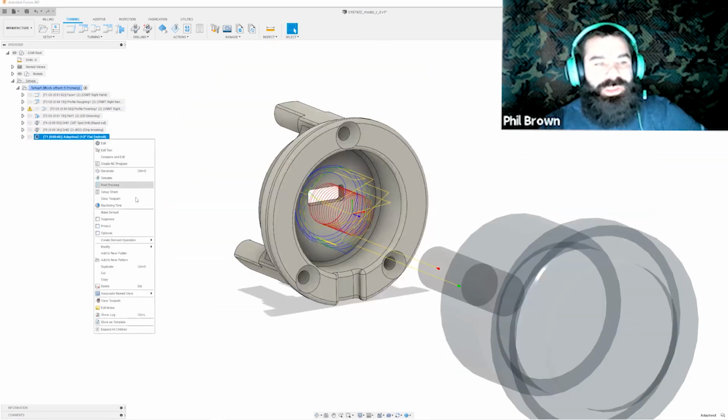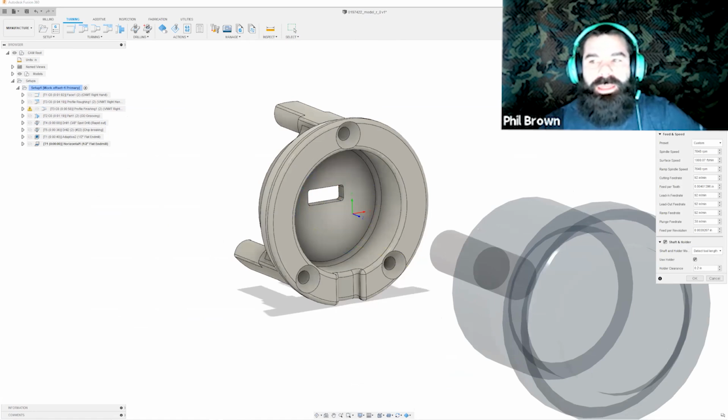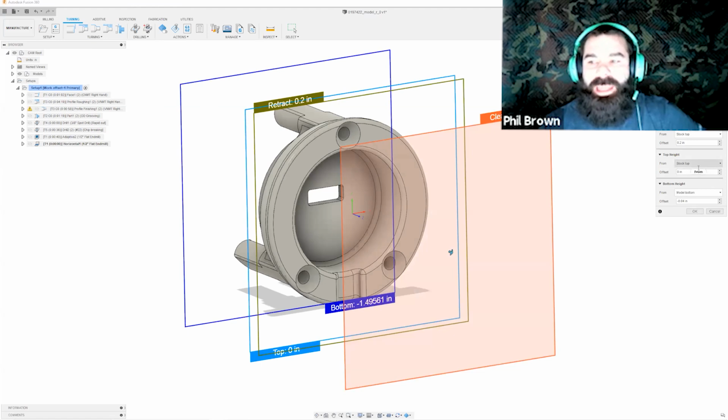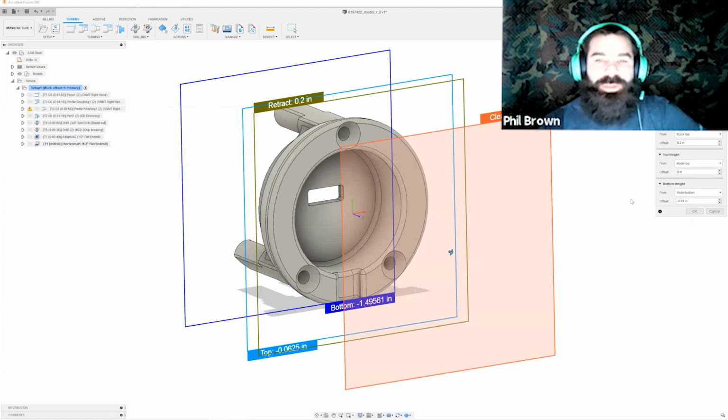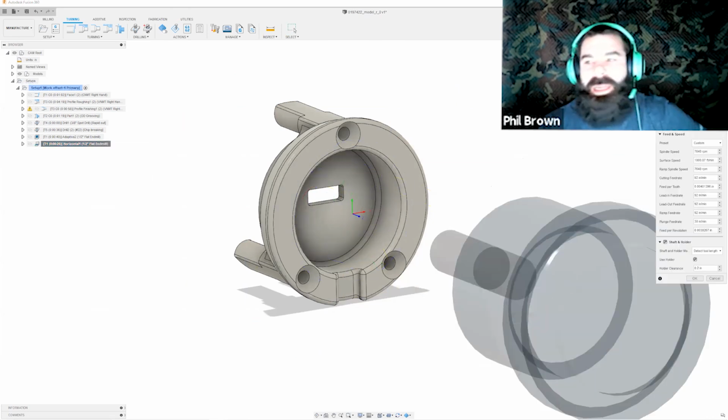I'm actually going to do what's called a derive this time around. Derive allows me to actually pull information from one tool path into the next. So what you see is my silhouette came through my tool center on or inside boundary. I also want to keep this zeroed out inside a boundary. And then I'm going to go ahead and say, I want to work from my model top inwards. And the reason why is I want to try to avoid this top surface since we turned that top surface. I did get a little bit here recognizing that, so I can go back and edit that out.